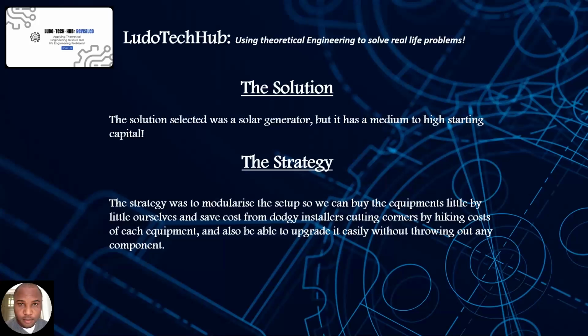So if you have a 10 kilowatt system that you want to design or install or build, but you cannot afford it, your whole load in your house will require a 10 kilowatt system, but you cannot afford that. The strategy I'm introducing here is go for a 3 kilowatt or a 5 kilowatt, whichever one your money can afford, but you're not going to load it to the same capacity as a 10 kilowatt.